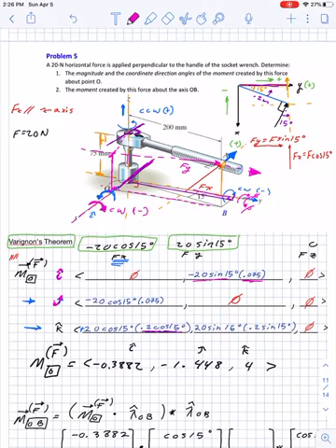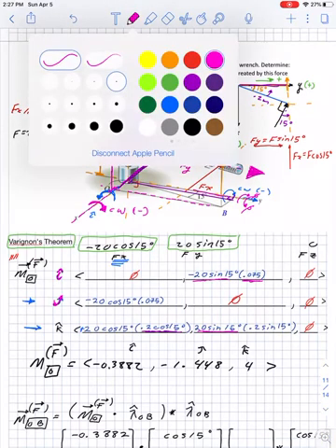So now let's see what's going on when this force is being pulled in this direction. What's going to happen to the z? Well, if I pull it, this thing has the natural tendency to move in that direction, and therefore it's also going to move in the counterclockwise direction, which is positive. And that's where we get this positive force, Fy, multiplied by, well, let's think about the moment arm here.